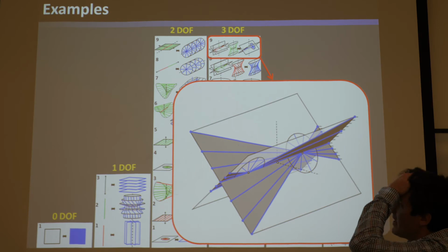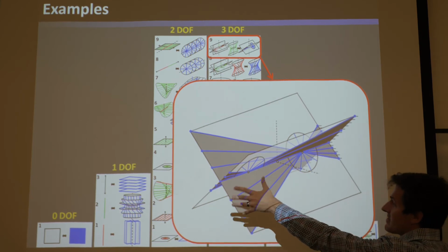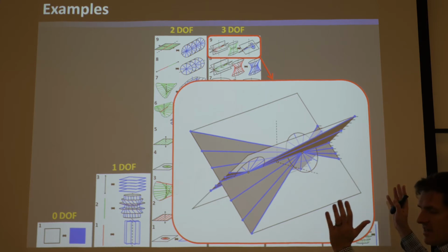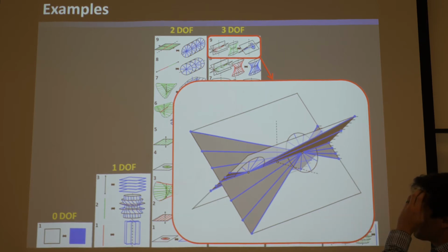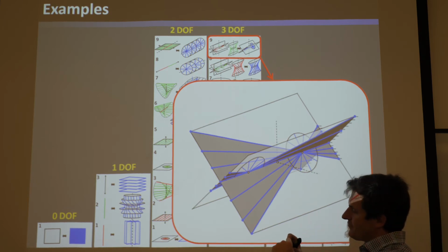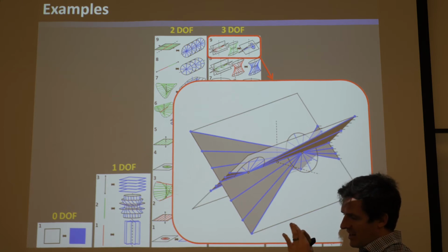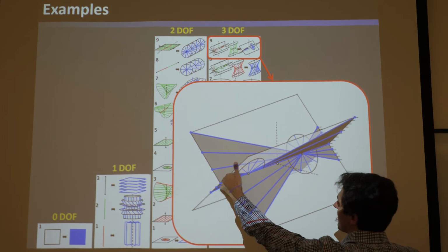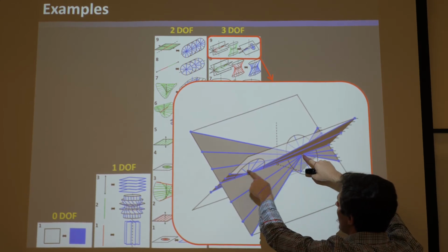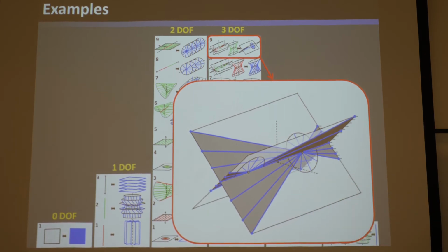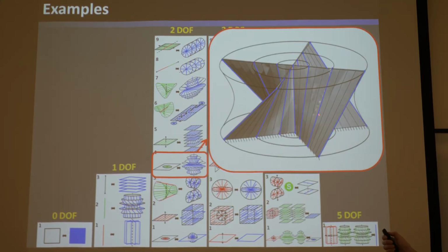It'll be an element, and it'll certainly be parallel because its entire geometry satisfies those two conditions. Blue lines connect them, they don't exit the geometry, and they fill it entirely blue. And they're basically like two of those V blades, except they're kind of offset. This is like a V blade here, and that's like a V blade here, but they're offset. So you can see how it would achieve that freedom space.